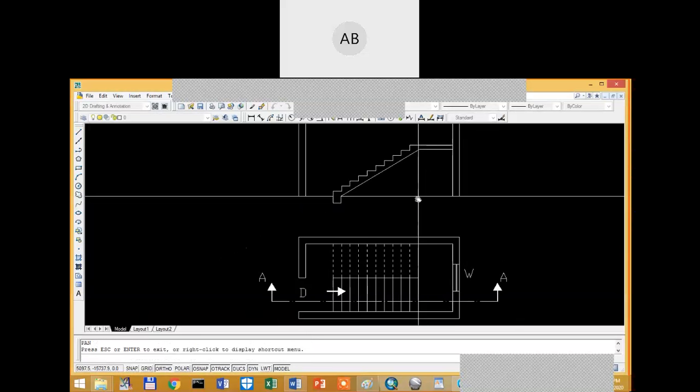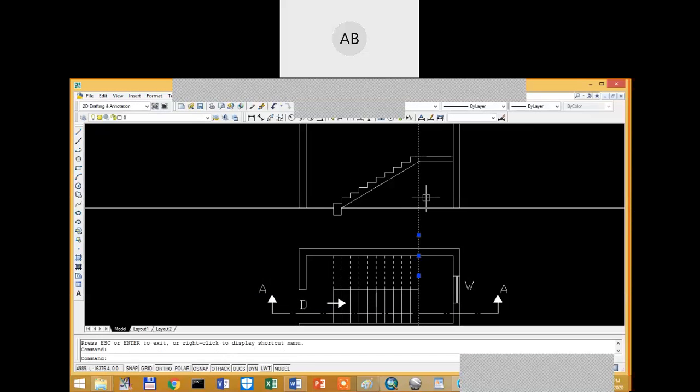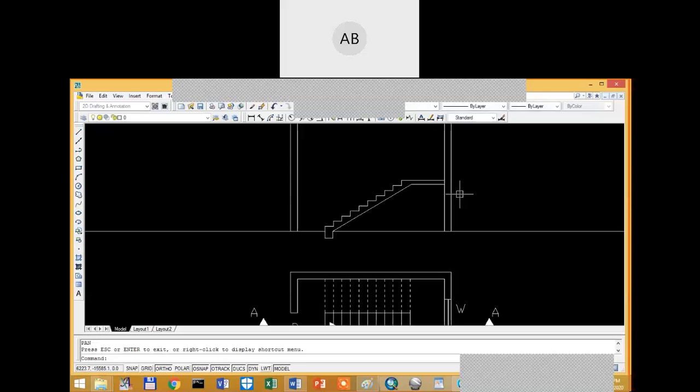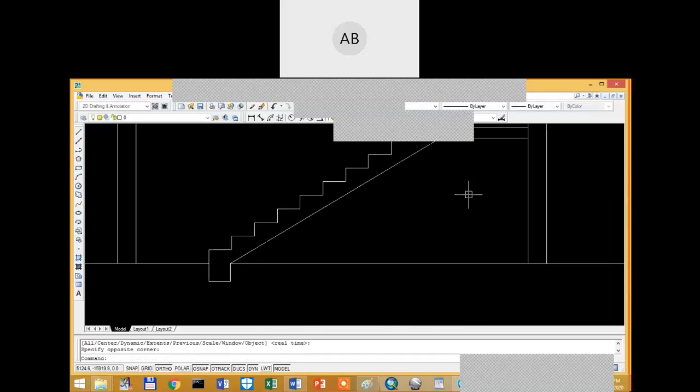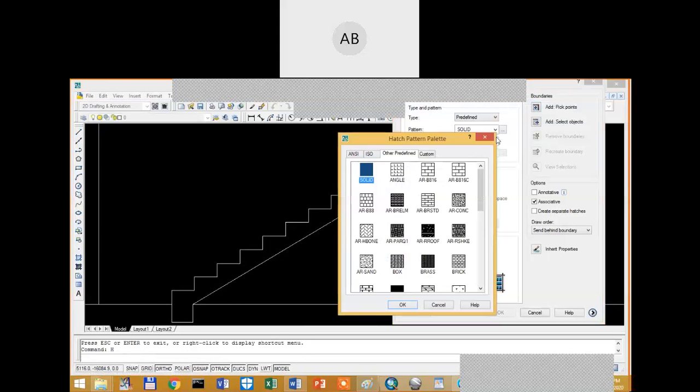Remember, we are drawing the sectional view. So along this stair is being cut, and then it is presented here. You have to give proper hatching in these vacant spaces. If you cut these, you will normally not find bricks. Mostly you will find concrete. Now we should give proper hatching of concrete here. By page, pick up the point.